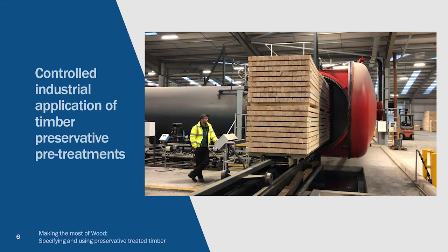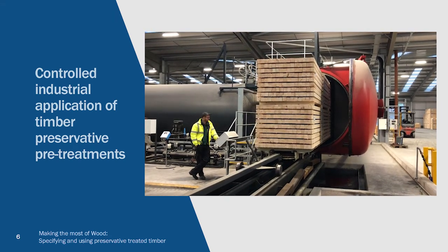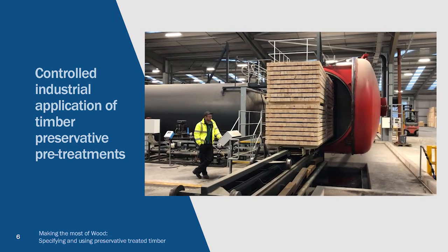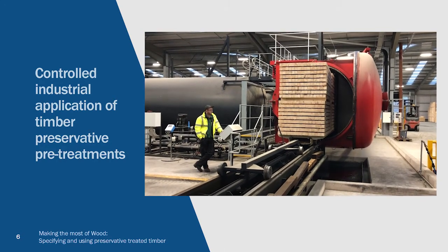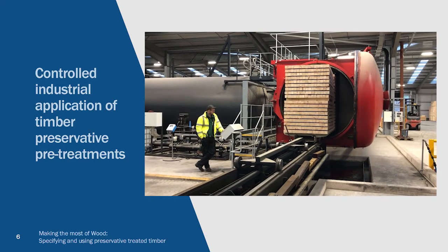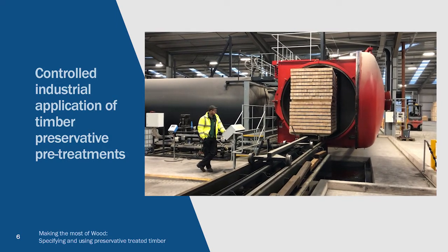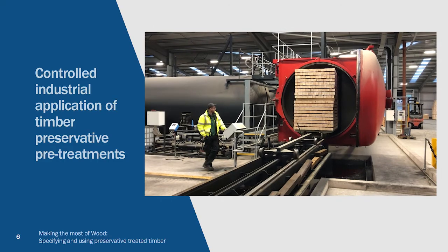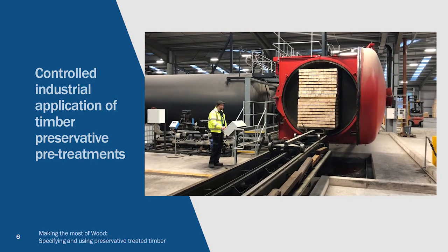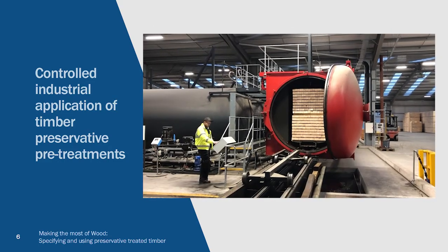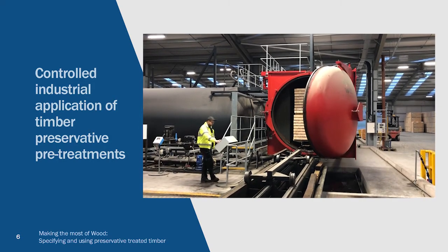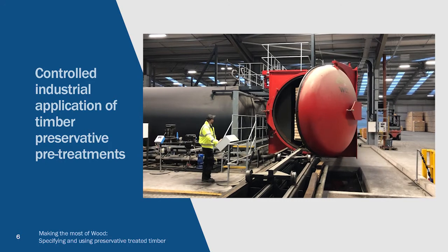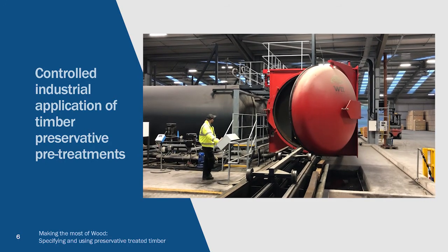The level of protection conferred by a wood preservative depends on its method of application. Brush, dip or spray applied products will afford a degree of protection, but for extended service lives of 15, 30 or even 60 years, typically only wood pressure pre-treated by an industrial penetrating process can give the required level of protection for the life of the component.